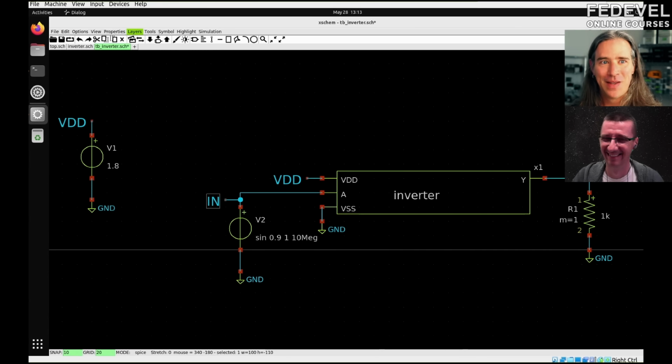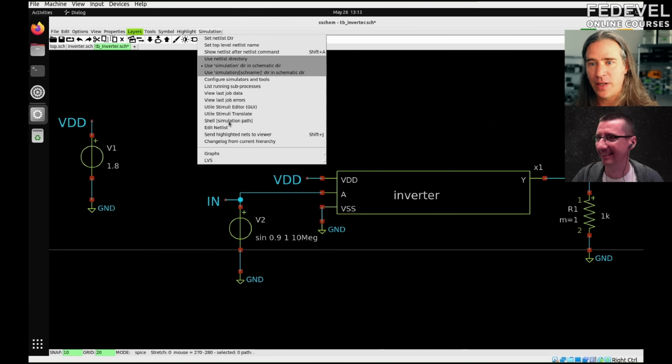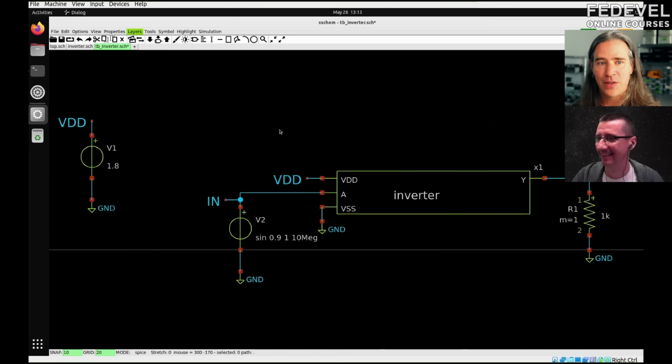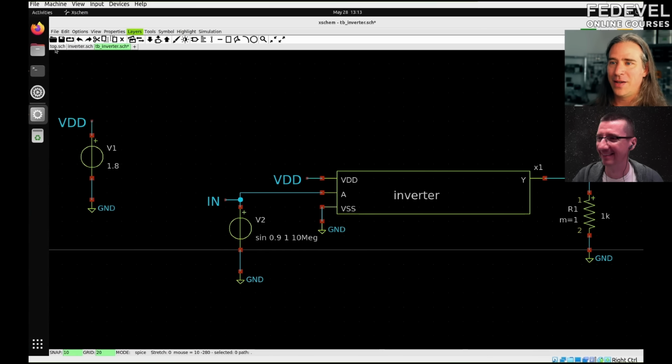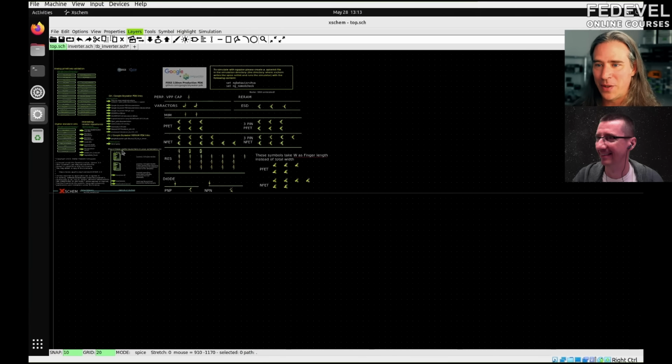We will see. So let's look at the net list. Okay, so I'll generate it and you can always look at it or edit it. So what I did was generate that net list. It gave me my voltage sources. It gave me this stuff. Now I could have made mistakes. It's not doing any checks. ngSpice will tell us. Oh, and I don't have any spice. That is important. I have a net list, but no spice.